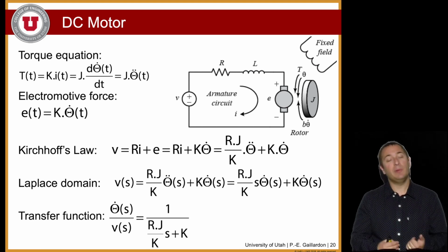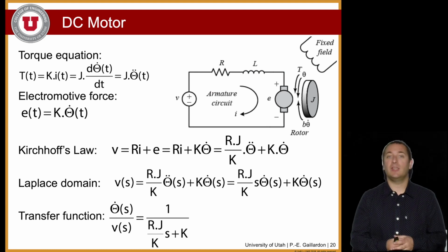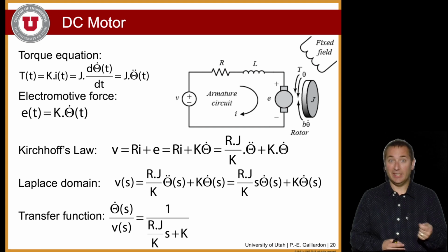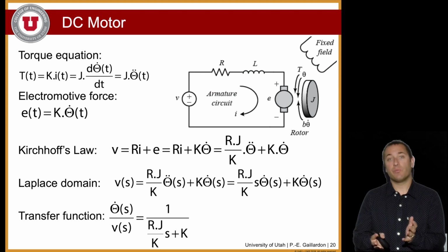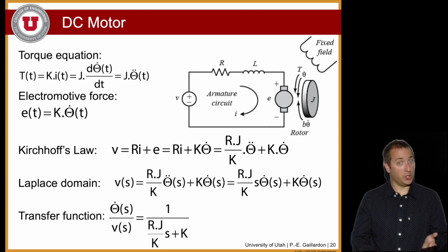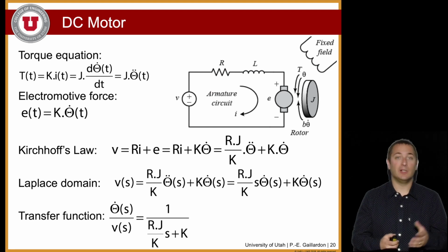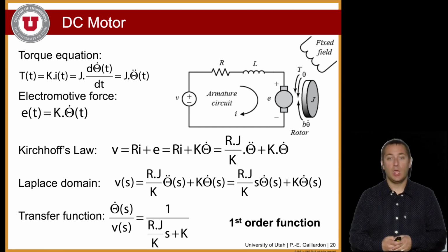So you'll be able to simplify this second order equation to a very simple equation that you'll be able to rewrite as a transfer function linking theta dot, the angular velocity, and the voltage applied across your motor. And what you'll get is a first order transfer function that will show a response of the first order, typical of an RC system.